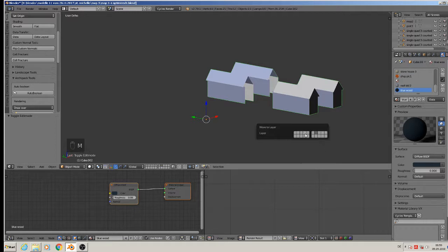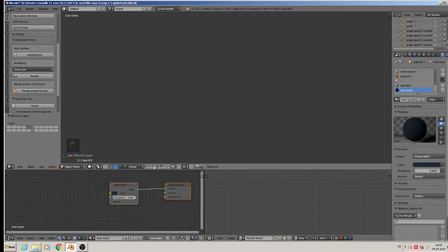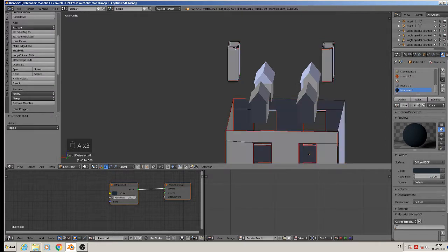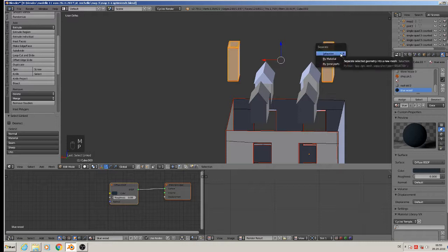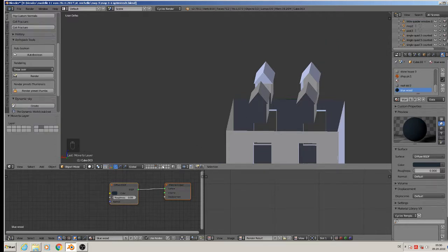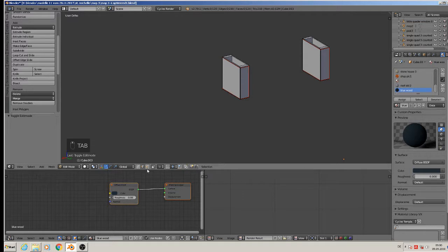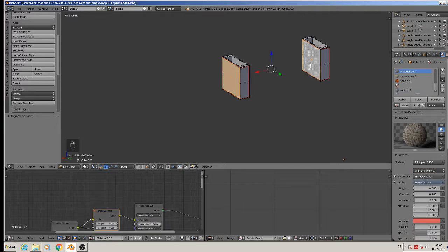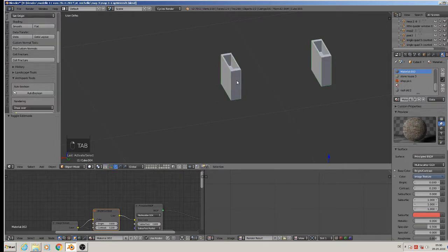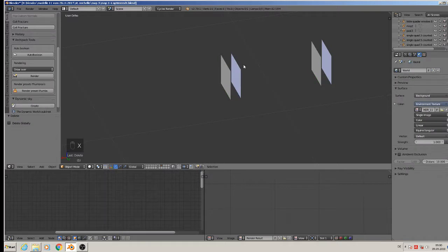We move them to the 5th layer back. So we have that. We take this oven here. They have too many vertices, so move them to the 7th layer, but before, separate the selection by pressing P, and then M to move to the 7th layer. We go to the 7th layer, we see what we want to have, that is that, and that, and that, and that. So we simply P separate the selection, then we can delete these ones and only that is left.